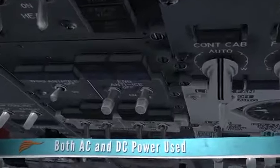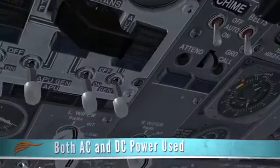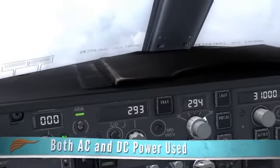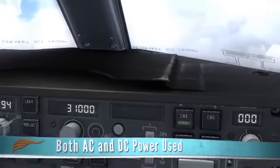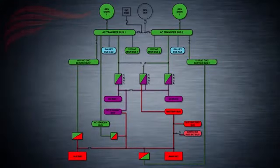The 737NG uses both AC power from engine-driven generators and DC power that's stored in a main battery and an auxiliary battery. Before having a deeper look at where the 737NG gets its electric power from, let's talk about the available electric buses on it. The AC electric system has two primary buses that take all the generated AC power and divide them amongst smaller AC buses. AC current is supplied as 115-200 volt 400 Hz power.